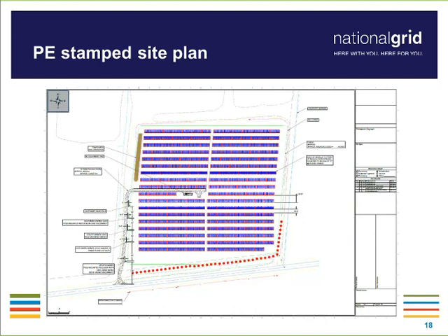And then, of course, we show the PV array and all that equipment shown out graphically, and that's good. Then we would be interested in the path of connection from our location, where we would have discussed the pole location or the tapping point of our line. And we see on this drawing it shows the different pole arrangements as they travel down the access road, with dimensions on distances between the poles. So we can get a good understanding and agreement on how far everything is spatially separated as it travels down, to make sure the engineering that goes into this drawing is going to be constructible.